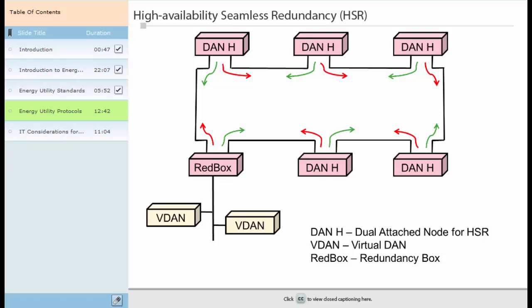From the switchover time perspective, HSR operates the same way as PRP. It sends duplicate frames to both ports of an HSR network. In the case of a failure in one area of the network, transmissions are sent by other parts of the ring. This approach provides zero switchover time and does not necessitate two parallel networks. On the other hand, an HSR topology requires a ring form, so it is less flexible from an installation perspective as compared to PRP. Another drawback of duplicate transmission is that only 50% of the network bandwidth is effectively used for data traffic.